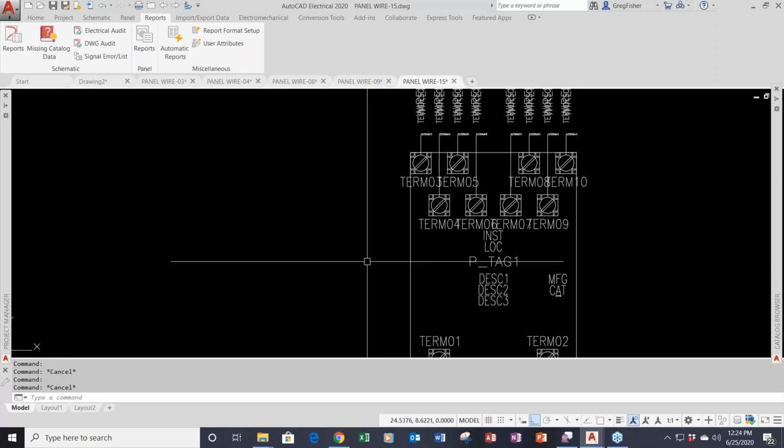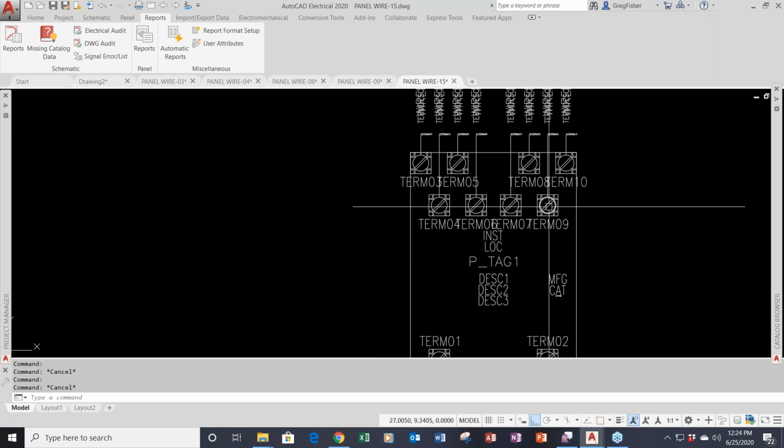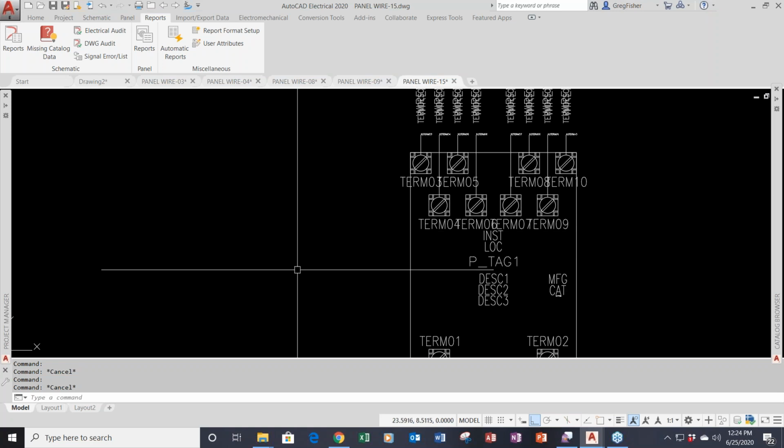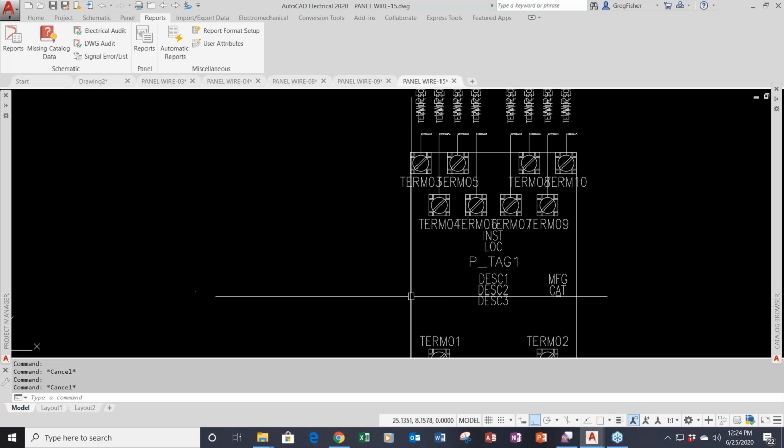And then here, this potentially could be, let's say, a 4-contact relay. I'm only utilizing 2 of them on the one that I inserted. But if I continue to insert more, then it would pick up these other terminals, which are the actual contacts.